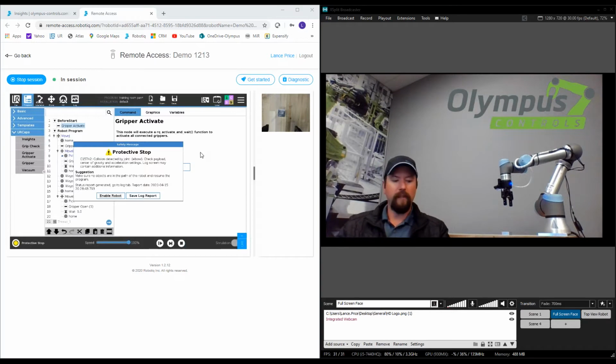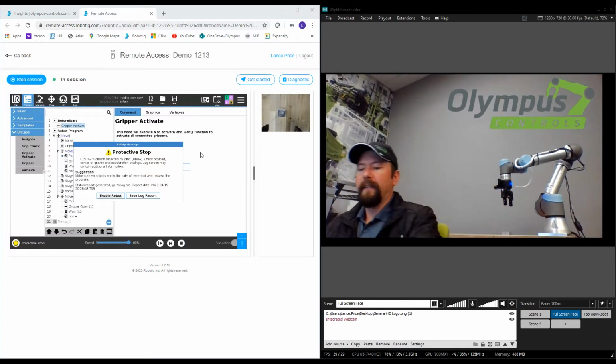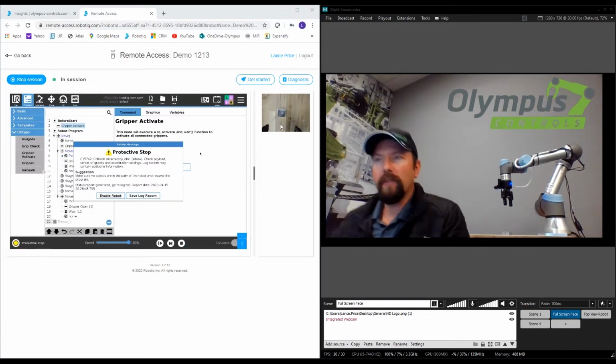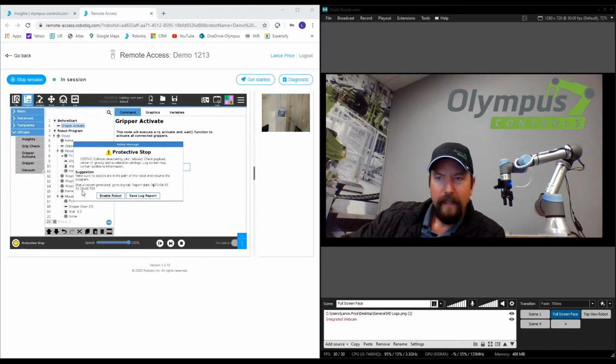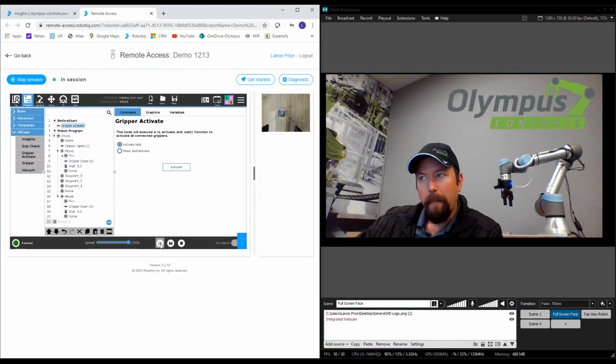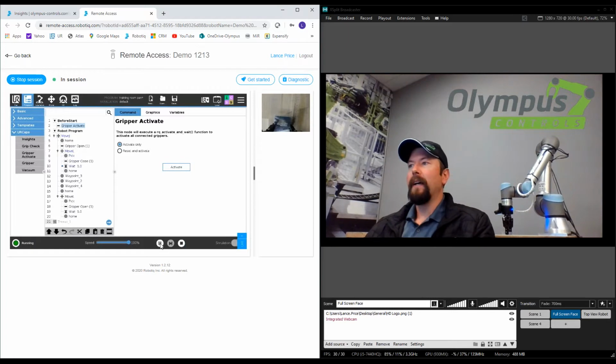So you may have just heard my phone going off, and that's my text that was sent to me by the robot via Insights. So now I could go jump down in front of my screen and take a look here. Okay, I've got a protective stop. I'm going to enable my robot and continue on with my program.